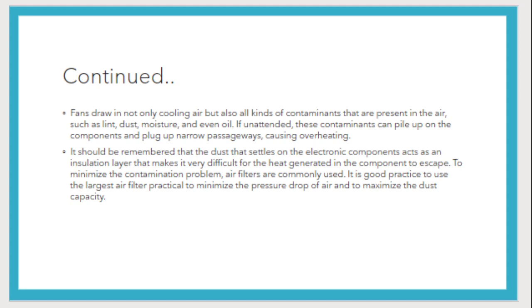To minimize the contamination problem, air filters are commonly used. It is good practice to use the largest air filter practical to minimize the pressure drop of air and to maximize the dust capacity.